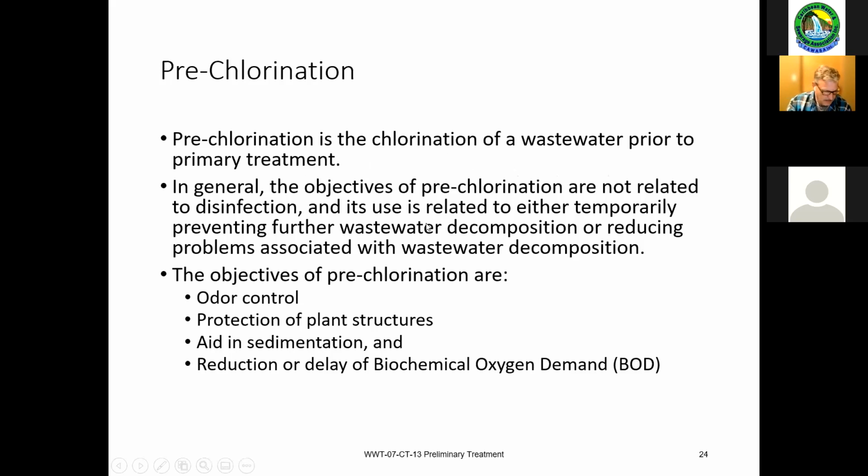Pre-chlorination can be used as well. The big objectives there are odor control, changing the sulfides, and protecting your plant structures. It does aid in sedimentation a little bit and reduction of BOD. That reduction is all designed around keeping the wastewater fresh. You need to have it fresh so it gets to where the organisms can work on it effectively.